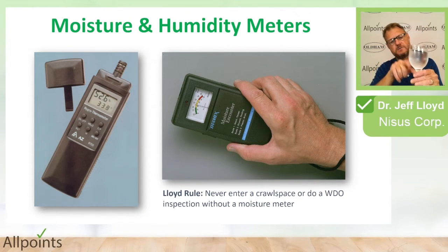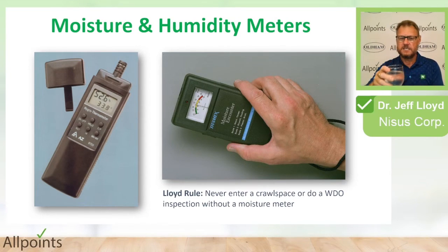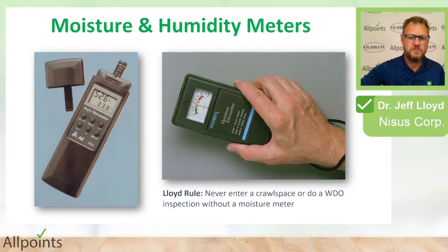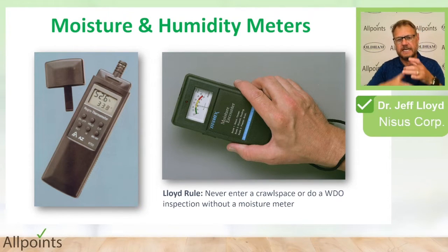Here we can see a glass with cold water, and so it's wet on the surface. The example I like to use is a bottle of cold beer taken from the refrigerator on a sunny day. It will sweat, the same deal. And dew point's important, and it goes hand in hand with relative humidity because of condensation in especially crawl spaces due to air conditioning use. Most people don't realize, but the safe temperature to use air conditioning in the southeast is probably about 76 degrees Fahrenheit. So if you crank your AC to 70 degrees Fahrenheit, you're probably causing a problem in your home, and I'll show you some of those problems.